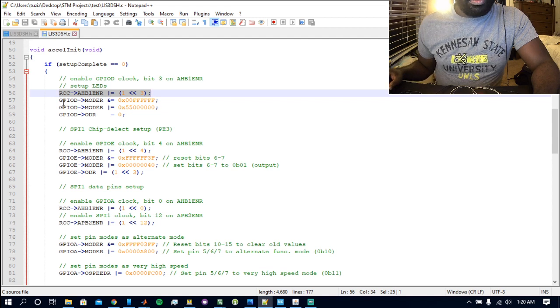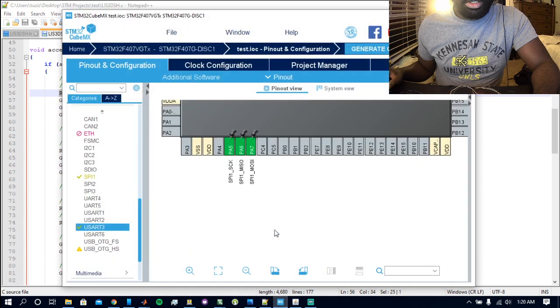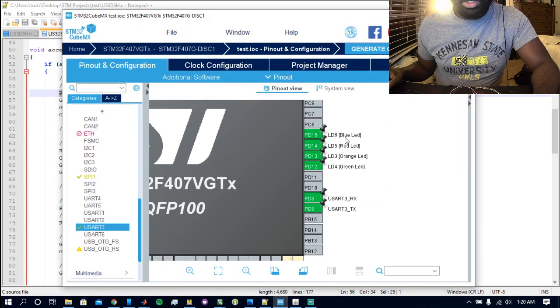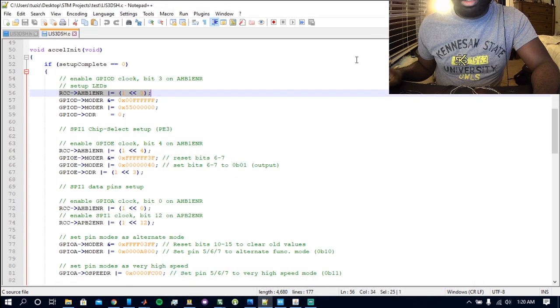Oh, no, I'm sorry, this is actually peripheral D because they're the LEDs. So it will be these ones here. It enables the peripheral D clock.